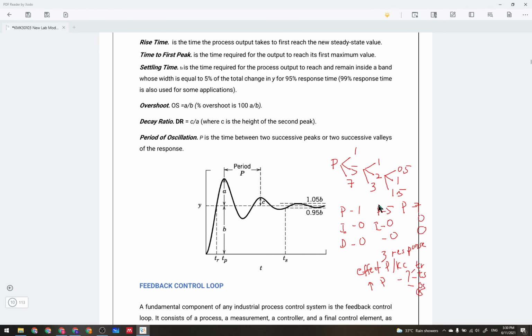And then you repeat the same procedure for the value of I. Let's say you choose the value of P equal to 5. So the settings should be 5, 1, 0, which are the values of P, I, and D. The second one should be 5, 2, 0, and the third one should be 5, 3, 0.